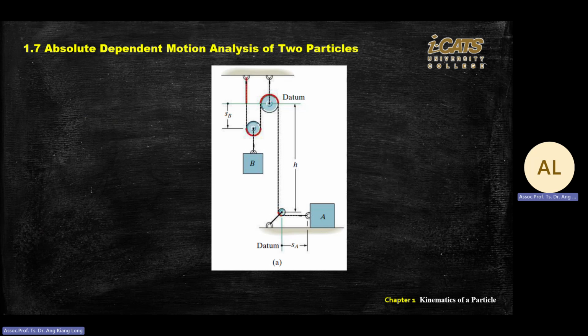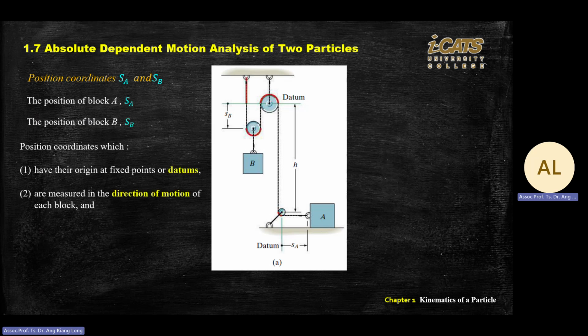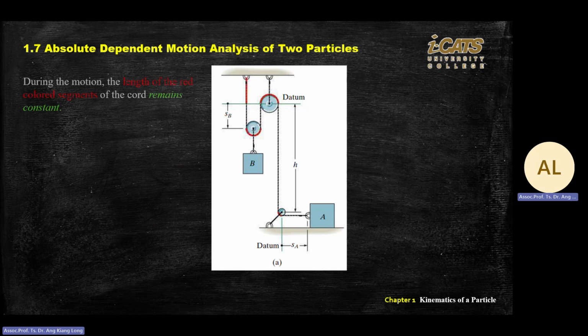And then look at the datum. Datum is on the top here. And observe the direction. B going down is positive. A datum here is here. So datum positive here. So from the derivation, you know there's an opposite direction between A and B. So don't simplify the minus sign. There's a meaning of the minus sign. Okay. So try to observe. This one you read.